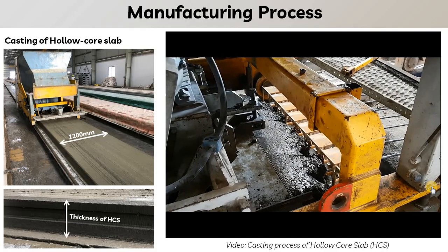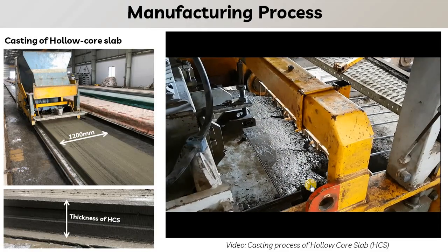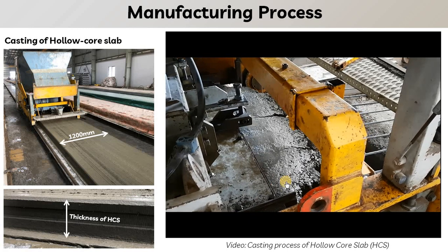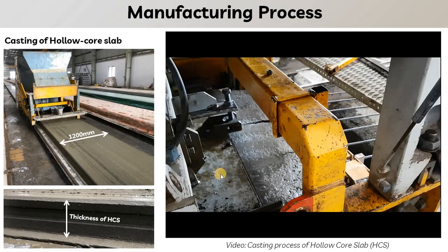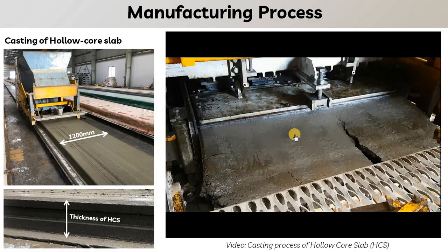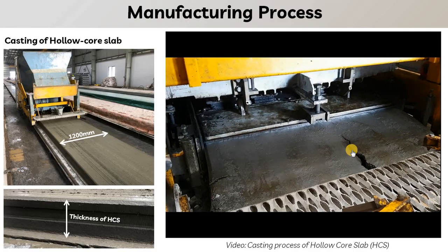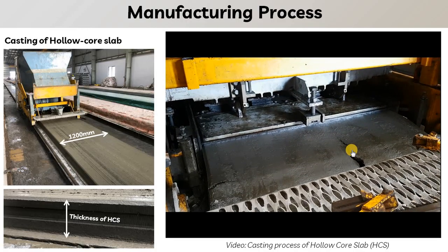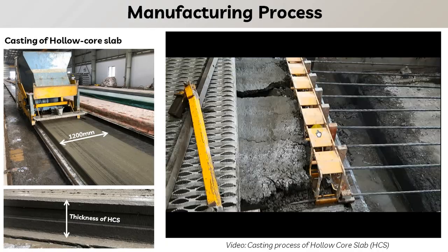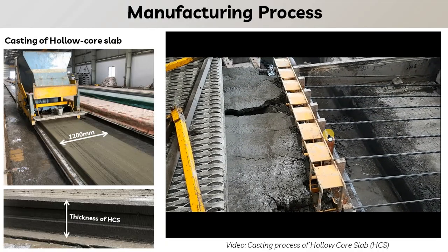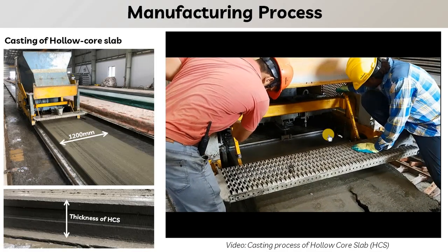Here on the top the smoother plate is working, and on the sides you can see these are the side formers that are used to create the side shape, as well as the top smoother plate. Up to here it will be waste, because it will not suddenly create the shape of the slab. From here you can see how compacted and very nice a slab has been created.